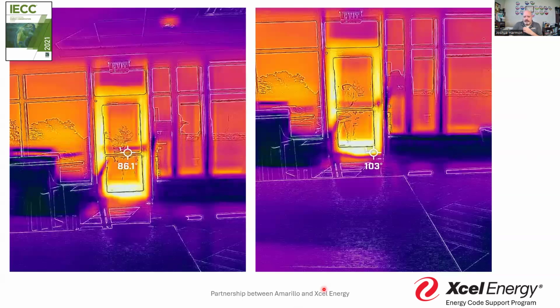And so if we have a building, let's say a multifamily or mixed use occupancy, with an interior surface, but some doors that aren't properly sealed or weather sealed, what we'll see is a huge swing, a 20-degree swing in that space. So that space is going to get hotter than it's supposed to, get colder than it's supposed to, depending on the weather pattern. Those are the things that we can identify and then identify corrections, because we understand why we're doing it. We're trying to control the air movement so that our equipment works efficiently. And so when we identify and verify that thermal envelope, this is part of what we're looking for.